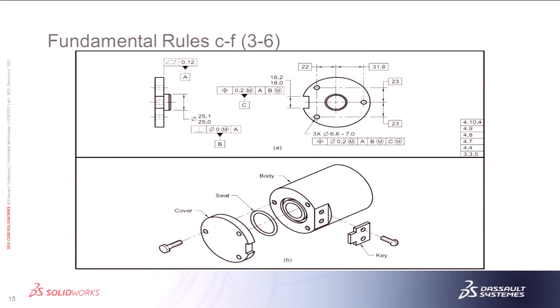So when you get back to functional dimensioning, that is something we like to talk about. You notice we've got the flatness callout on the mating component where it mates to this part. You've got the perpendicularity to ensure that it can insert into the mate on the other component.